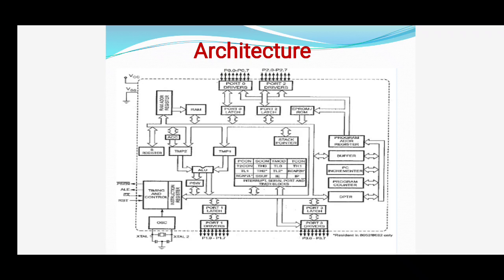The accumulator is an 8-bit register and takes an active part in ALU operations. ALU stands for arithmetic logic unit, responsible for all the operations performed by the 8051. The result of the operation is stored in the accumulator. The ALU takes input operands from the temporary 1 and temporary 2 registers.